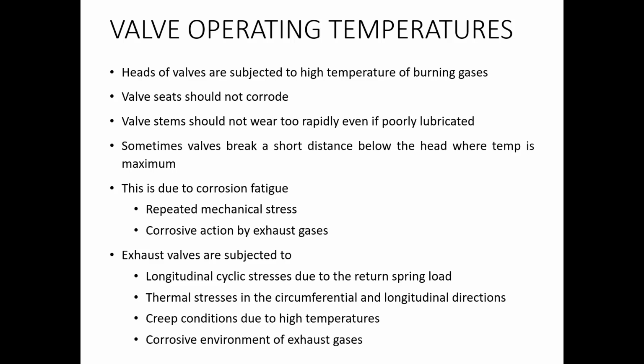As I mentioned, there is cyclical stress, along with high temperatures and the chemical corrosive action of the exhaust gases. The exhaust gas contains many compounds of sulfur and nitrogen which can corrode the surfaces at high temperatures. So due to this corrosive action and cyclic stresses, corrosion fatigue failure can occur, due to which the valves may break after a point of time.